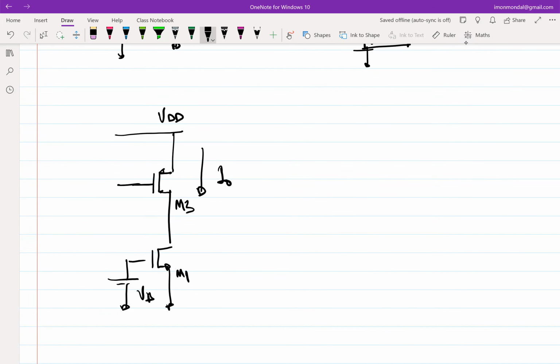So what should I do? Assume that you have a master current source somewhere, or you don't even have to assume. I mean, copy that required voltage at that point. Essentially, I have to leave the drain as is. If I connect the drain with the feedback, then I am losing output impedance. So I cannot really do anything like this.